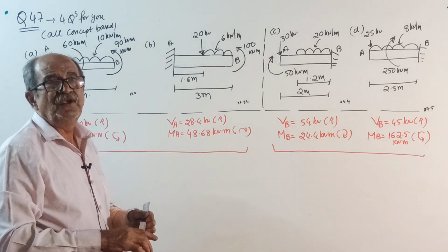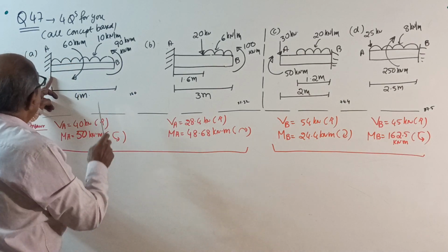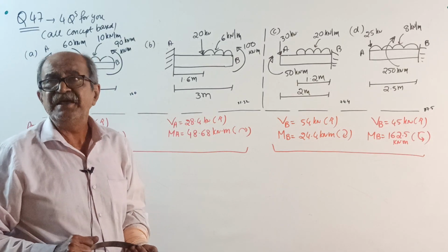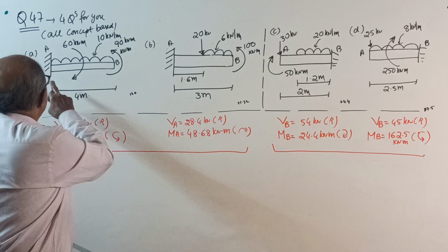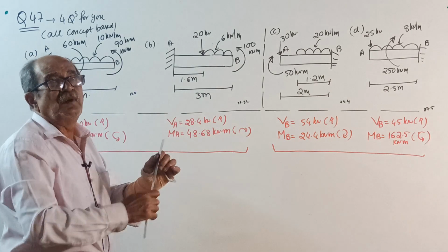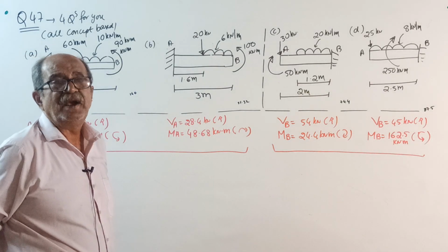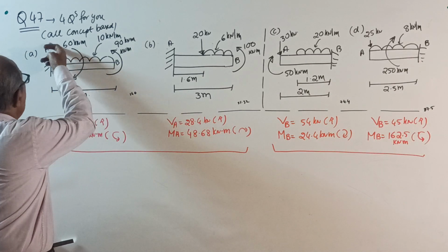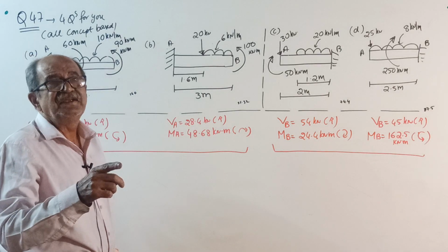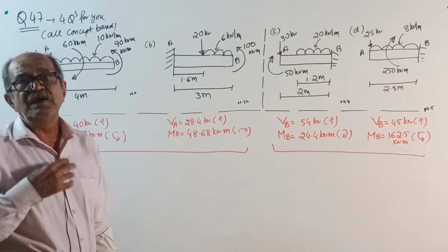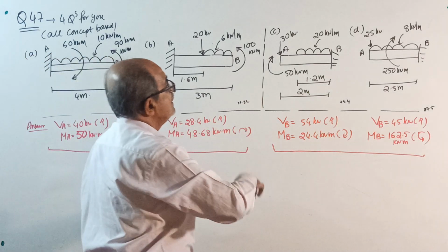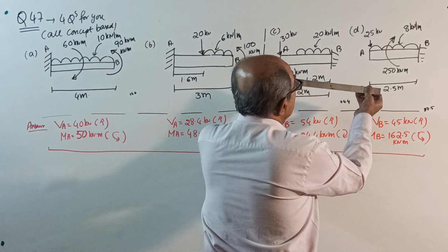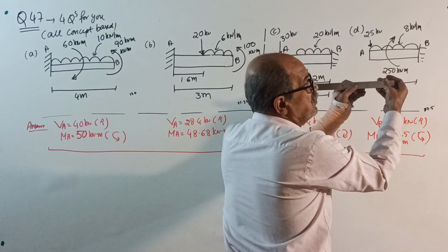Now, what you have to do is, about the fixed end A, if you are going for direct calculation, decide what is the net clockwise moment and what is the net anti-clockwise moment. If net moment action is clockwise, reacting moment will be anti-clockwise. If net action is anti-clockwise, reacting moment will be clockwise. Here, loading and couple: you decide the net effect about the right support, fixed end.